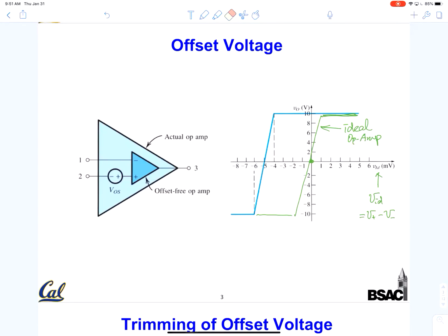However, this is an analog circuit. An analog circuit actually needs quite a bit of tuning and matching of the transistors. Towards the end, you should be able to understand why there is offset voltage. In a nutshell, the main reason is that this relies on perfect matching of the transistors in the pair. The plus and minus input terminals eventually go to the inputs of a transistor pair.